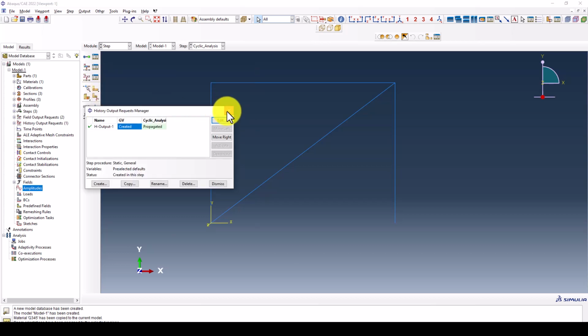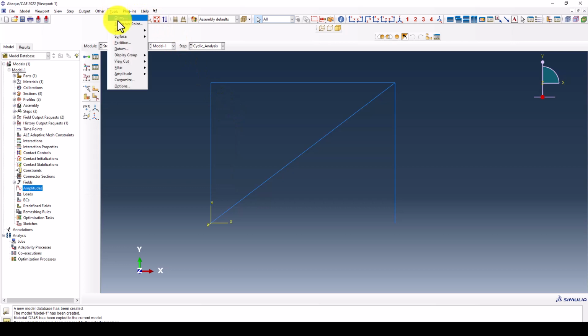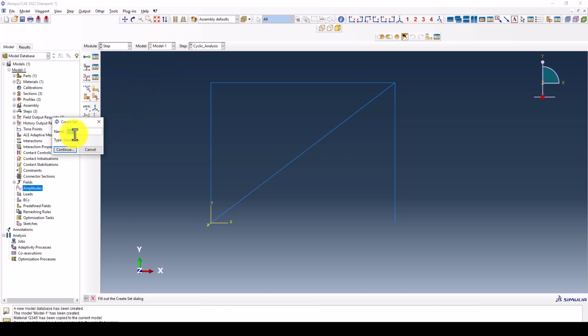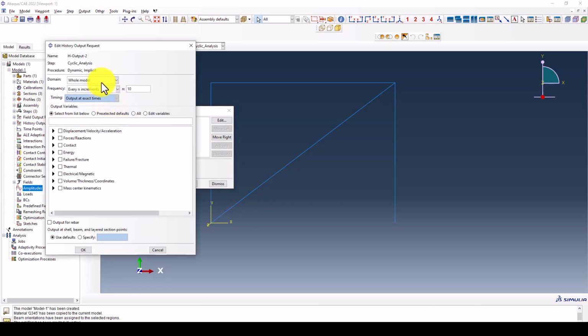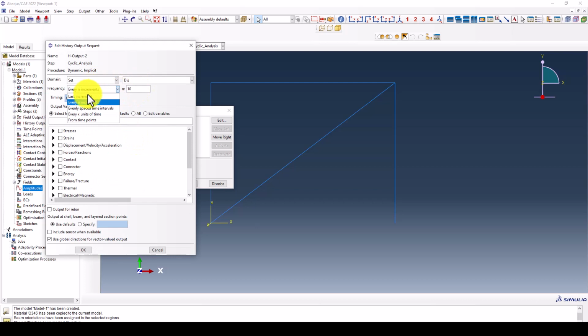And for the time history output, we're going to go back to here. We want to first create a node set, something called displacement, and I want to take this node and create one output at that point. When I put the displacement at this point, exactly this point will give me a reaction force as well. So I'm taking the cyclic step and asking for that set, and the increment should be 0.5.